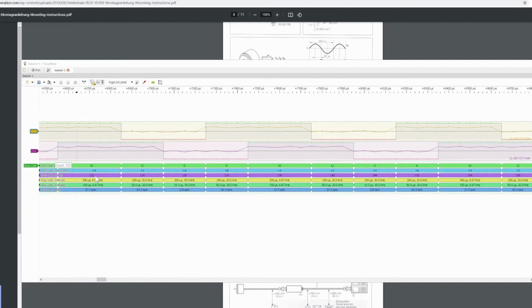This counts. This is actually the encoder counting. So this capture is all going in the same direction, so it's all counting up. If I were moving the encoder right and left and right and left, the number would be going up and down. But this is the processed count. And then you can see the pulse time and the frequency of the pulses, as well as the averages of those. And then it actually translates that into an RPM reading, which is really interesting.